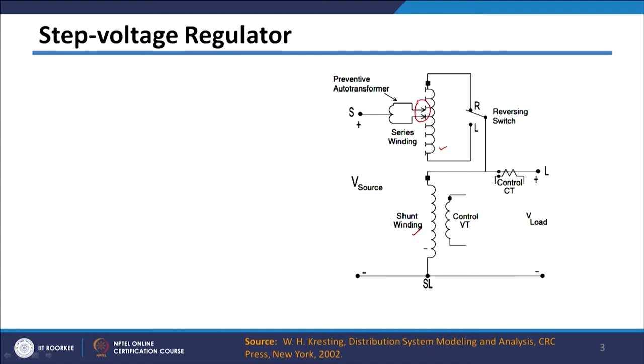and for changing the tap position we have this tap connection here, and for that we are using this reactor switching, because we do not want to interrupt the current whenever we are changing the tap. Whenever one tap is connected to the next position, only then can we disconnect the other tap. So we need this reactor here, which is used while switching, whenever you are changing the tap positions. So current continuity will not get disturbed.